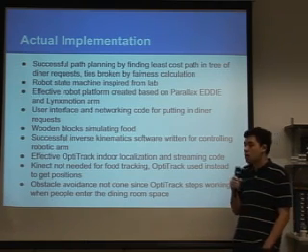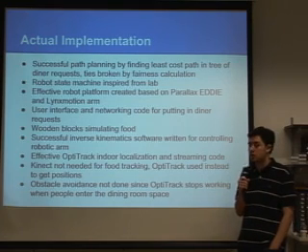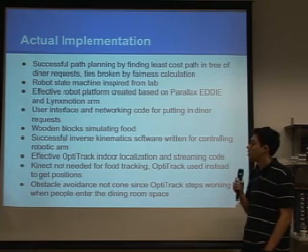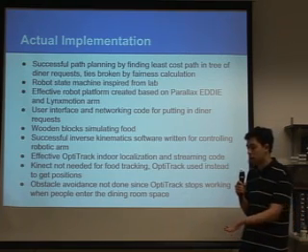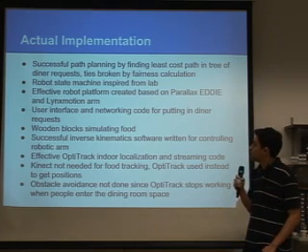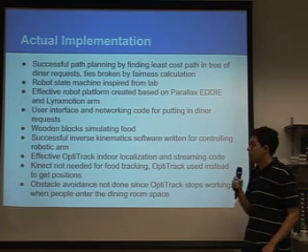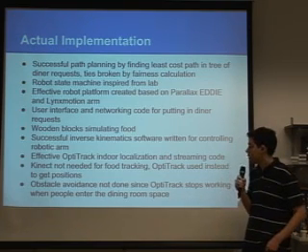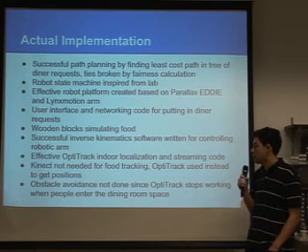And our robot is running a state machine that's inspired from the work we did in the labs before. Our robot platform is based on the Parallax Eddy, and we have a Lynxmotion arm. We have networking code and a GUI for putting in diner requests and the chef's table. And we have effective inverse kinematics code. We also are using OptiTrack for indoor localization, and we're streaming that to the laptop on the robot.